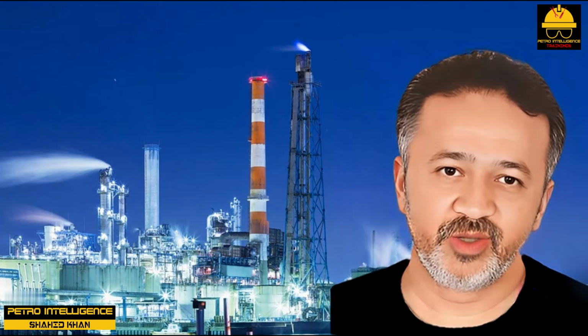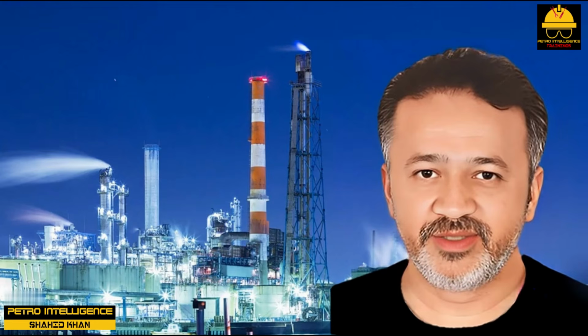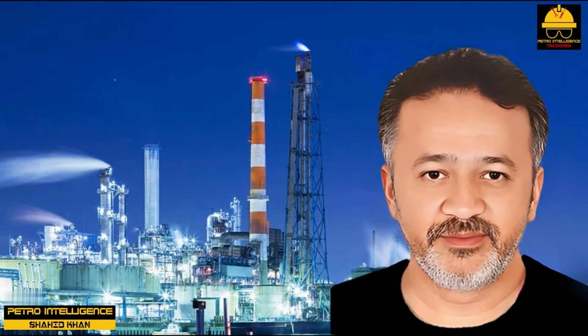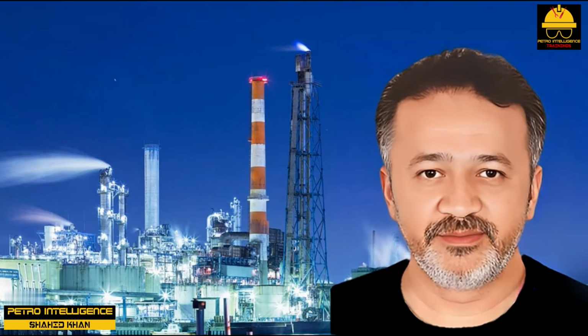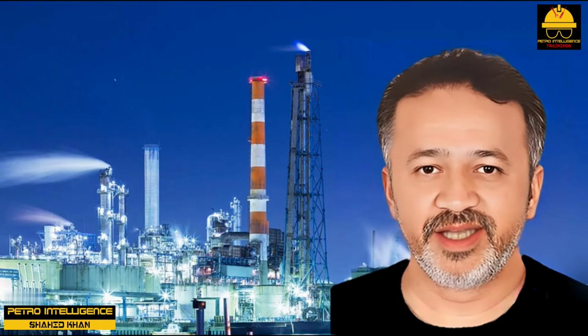If the compressor is suction volume limited, we say that it is speed limited. If the compressor is driven by an AC motor, its speed is determined by the motor speed and any connecting gears. If the compressor is driven by a turbine, then the rated speed of the turbine limits the compressor speed. Overcoming speed limits. While the actual cubic feet of refrigerant vapor to the compressor may be limited by the compressor's speed, we can still overcome this bottleneck.